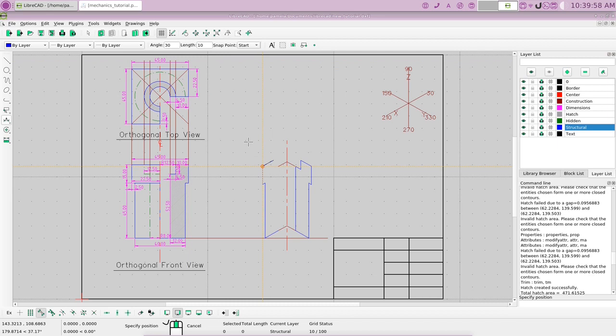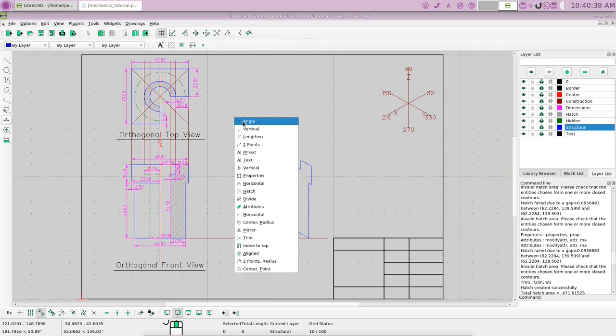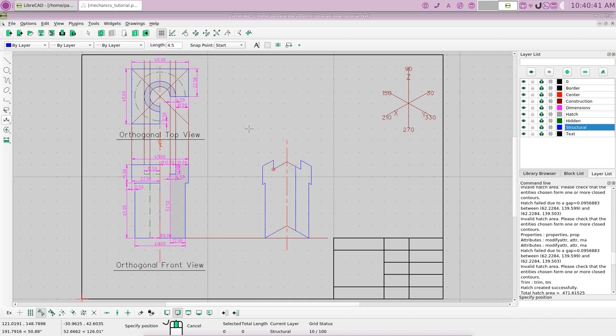Okay, and then a vertical line of 7.5, and change it to the other direction to there, and then an angle line of 4.5 and change it to the other direction right there, and then a vertical line, we could say, of 52.5, and that will go from this point down to that. Okay, so there you see we have the two faces of our drawing.